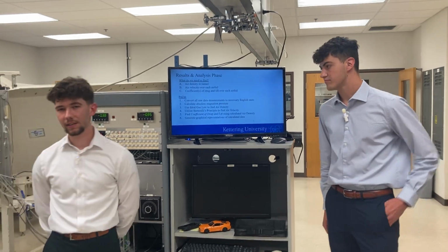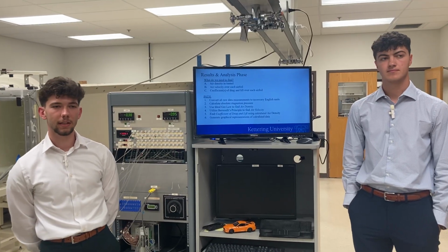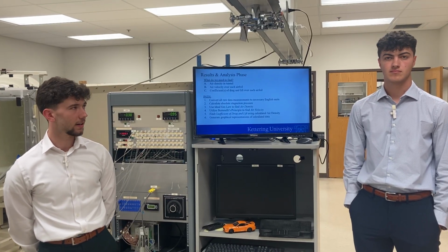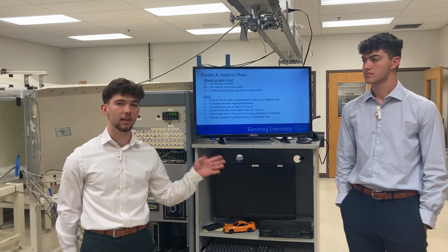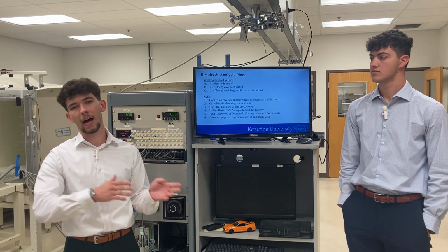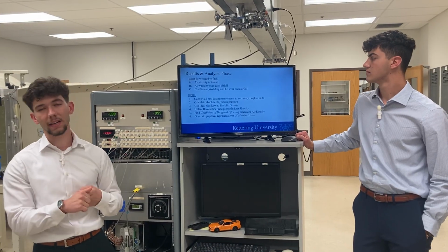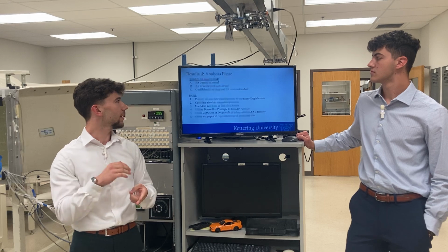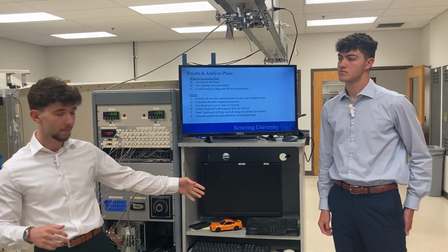So once getting the tested raw data, it was important for us to understand what values we needed to find and what path would be necessary to calculate those in order to draw conclusions about the applications of changing that aspect ratio on the other variables. So the main ones that we needed to find were the air density over top of the foil, the air velocity over top of the foil, and the coefficients of drag and lift over the top of each foil.